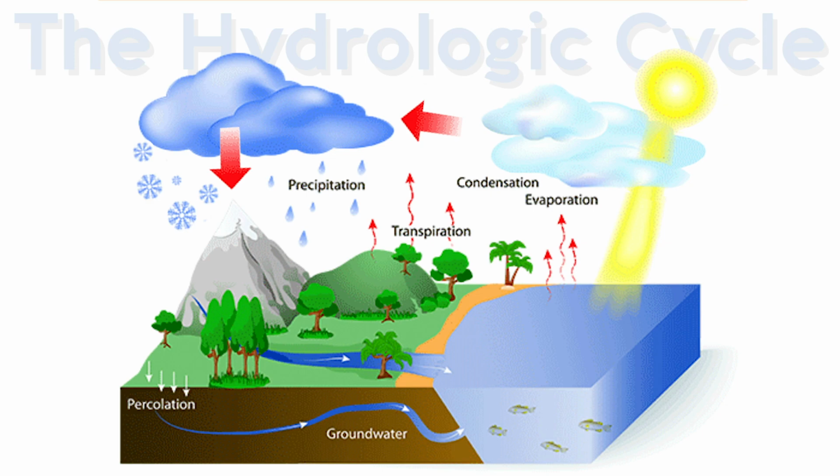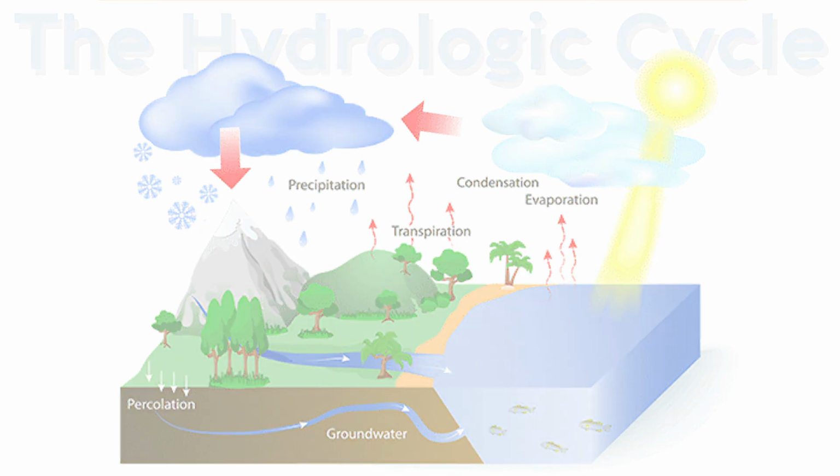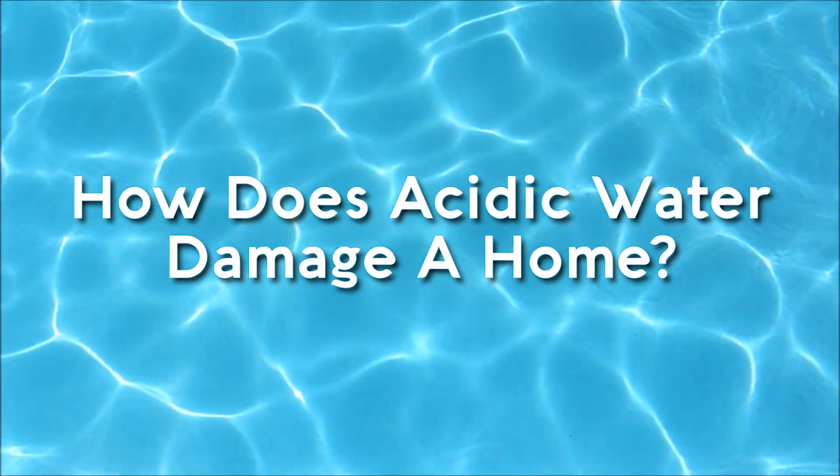And depending upon the Earth that it goes down through into our groundwater, it can become either higher in pH because it passes through alkaline-rich rock in the soil, or it can actually become more acidic due to the lack of those kind of minerals being in the soil. Well, when that happens, we need to do something to adjust that acid water back up towards neutral. The reason that we do that is because acidic water can be very, very corrosive.